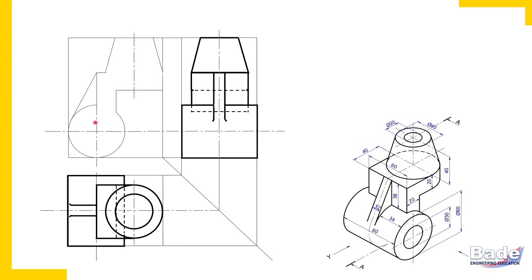So which two points have I revised here up till now in sectional views? Listen, if two portions get cut by a cutting plane, the boundary between the two is to be erased. So we have erased this boundary, we have erased this boundary. Okay, now let's make the boundary. You never get hidden lines at the boundary, so make the boundary dark. Check.